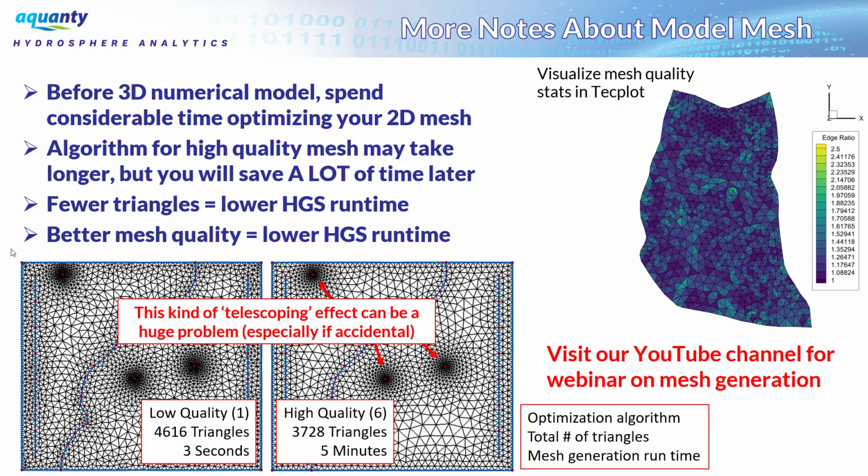And the fewer nodes that you have, the 5 minutes that you spend running a higher quality optimization for your triangular element mesh, you will very likely save hours after the fact in model runtime. Okay. So this is really foundational. It's important to take your time and construct a very high quality mesh.